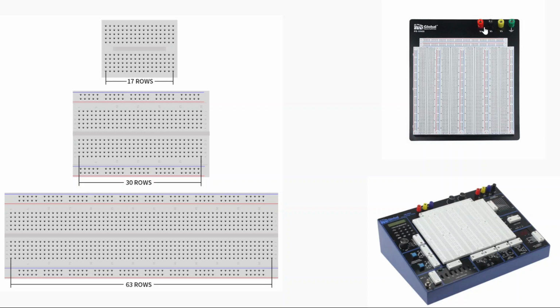where you can connect different power and ground on this side of the breadboard. When you connect power or ground to these terminals, they are not connected by any means anywhere here on the breadboard area. So you have to bring in a wire in order to connect with a power strip. On the breadboard here or here, it's pretty clearly visible. You see these red lines. You see this red line all the way?